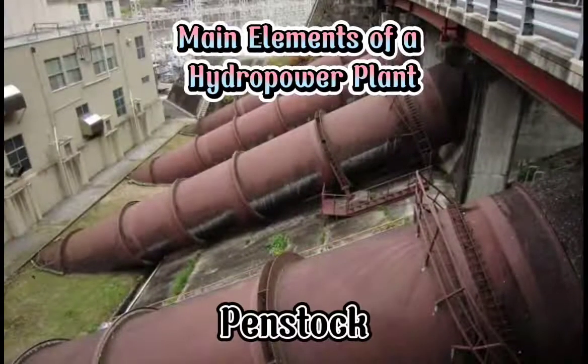Next is the penstock. The forebay or surge tank is connected to the turbine scroll case via a closed tube. Each unit is typically given its own penstock in medium head power plants. A single penstock is usually utilized in high head plants, and branch connections are offered at the lower end to supply two or more units.